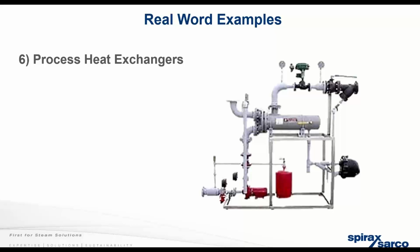So, looking at this, there could be 1, 2, 3, maybe 4 different types of water hammer in one system, happening all at the same time, causing you grief. So we've got the slug flow from the strainer. We've got modulating pressure going into a steam trap, which is discharged into some type of condensate system. I'm not sure what, but that may be causing a water hammer.